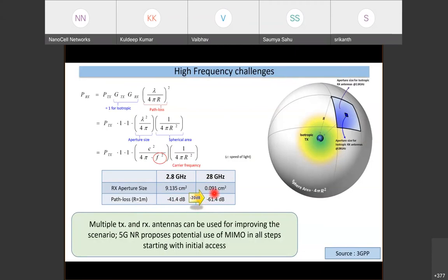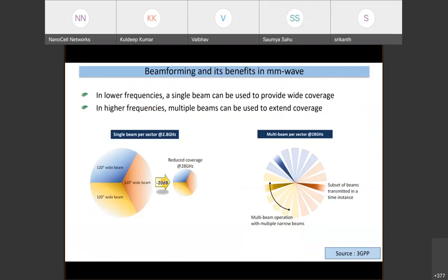So how do we solve that problem? There again, we have a similar idea as what we talked about in massive MIMO, but now we are just dividing the space into very narrow directions. It's almost like when you reduce the angular range of a spotlight, that spotlight can carry farther away. Instead of the example of a 3-sector implementation sometime back, if we did the same thing, that would be our coverage. Now look at our coverage when we have done finer beams.